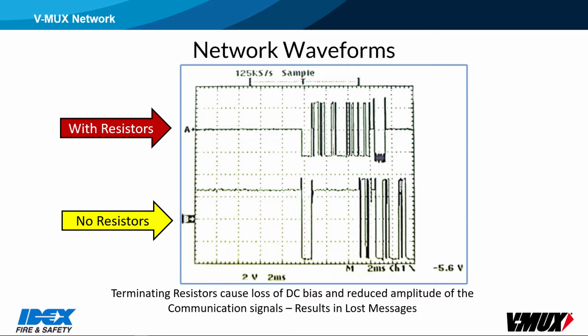A common symptom would be where the warning lights are enabled, and all of them turn on. When disabled, some will turn off but others stay on. That means that at least one node missed the message to turn those lights off. Other possible causes of that same symptom might be water inside one of the three-way splitters, or a single open communication wire somewhere in the network.